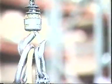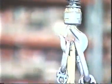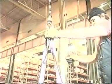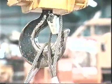Remember not to overcrowd a hook. Where multiple slings are being used, they should be attached to a shackle, which is then placed on the hook. This prevents the danger of the hook being strained owing to the spread of the slings, and also the danger of a sling fouling the safety catch or slipping over the point of the hook.